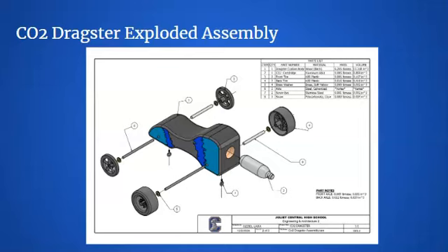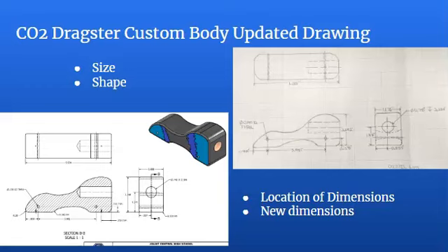But the thing is, I never changed the name of that model. Despite the front axle part file being called axle body, Inventor registered both axles as the same part. In order to solve this, I made a quick part note and wrote the correct mass and volume values for both of these axles.